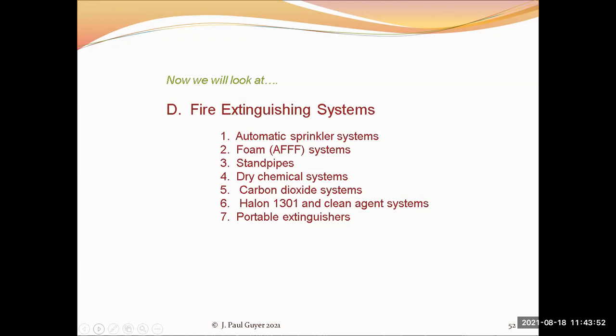And the water comes out in a foam, a bubble foam, and this is used in a situation where you have liquid fuel fires, like gasoline or jet fuel, things like this. And this foam floats on top of the fuel that would be burning, and it smothers the fire. And so this kind of a system, which is quite sophisticated, is typically used in a place like an aircraft hangar or maybe in a vehicle garage. And it's because the big threat is fuel fires, and you can't put those out with water.